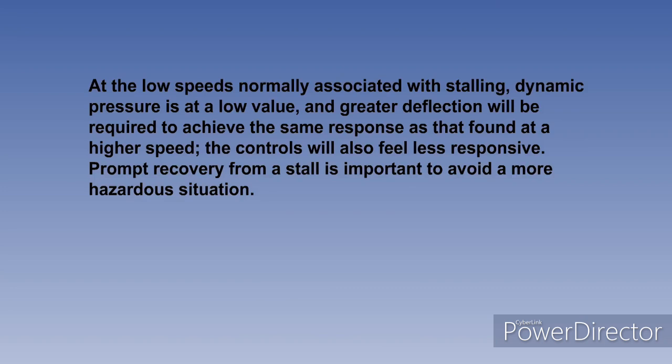At the low speeds normally associated with stalling, dynamic pressure is at a low value, and greater deflection will be required to achieve the same response as that found at a higher speed. The controls will also feel less responsive, as mentioned earlier in the lesson.